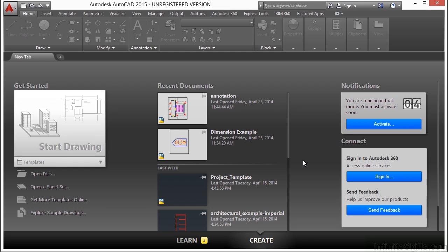Now, there are many different ways to use text, especially multi-line text. The method you will use will depend on your needs. Styles will control your font type. MText objects can be edited within the text editor, but keep in mind that once you do, you lose some editing abilities. Let's just start with a blank file.